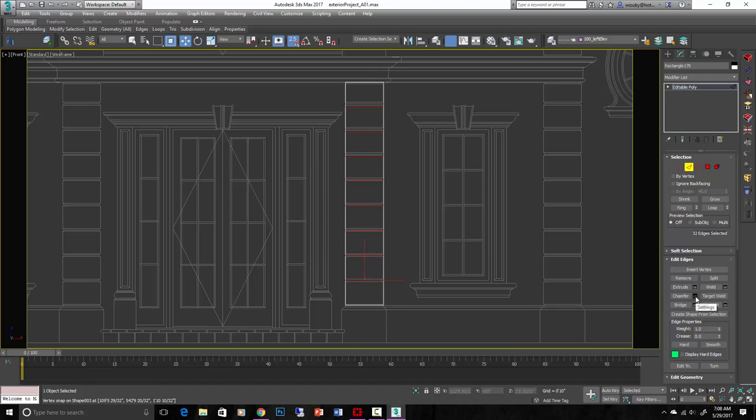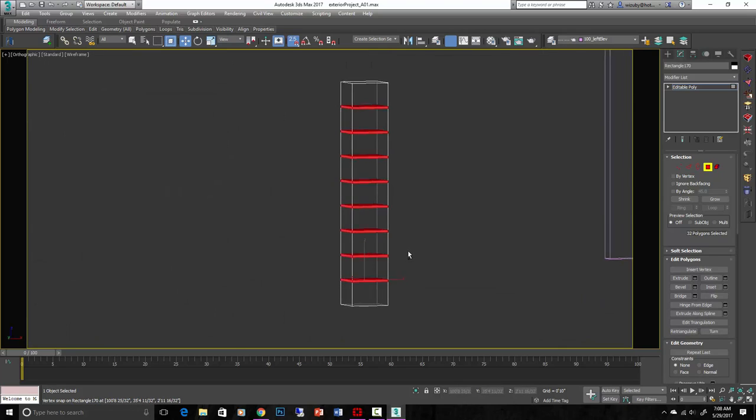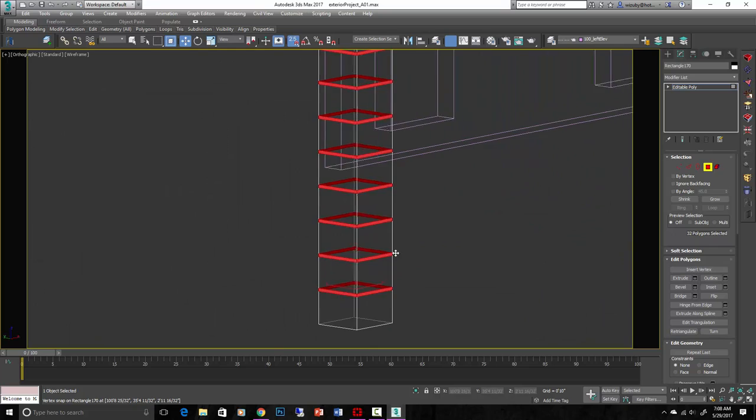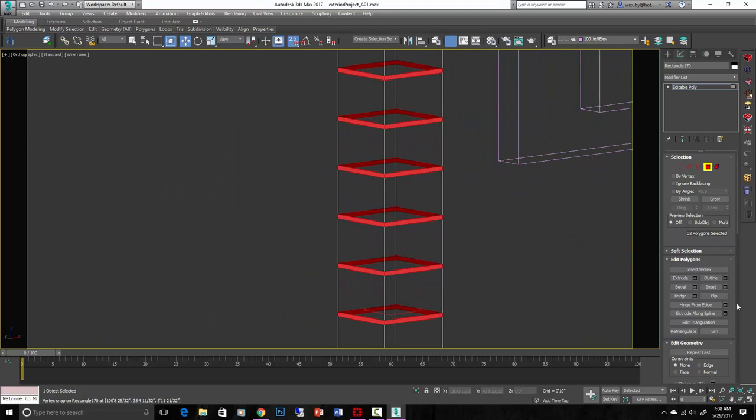And see if we can chamfer them. That kind of splits them up. And then select the faces that created. There might be easier ways to do this too, but I'm showing you some poly tools. Okay, we've got all those faces selected, and let's do a bevel on them.